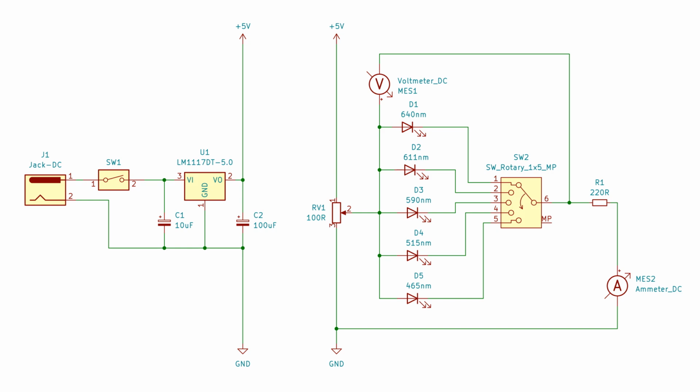The LM1117 is a low dropout voltage regulator. The device is available in 5 fixed voltages. I use the 5 volts version. The input voltage at the barrel jack is therefore regulated down to a stable 5 volts. The two 10 microfarad tantalum capacitors improve the transient response and stability.